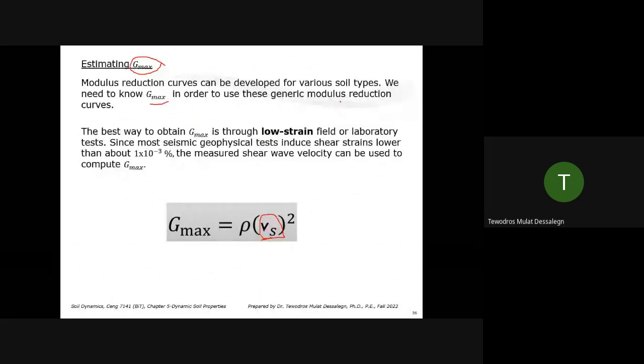Reduction curve. The best way to obtain Gmax is through low strain field tests. Those wave propagation tests we discussed yesterday.